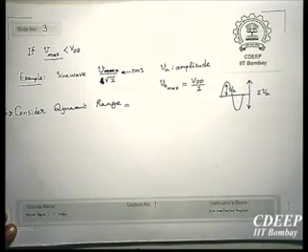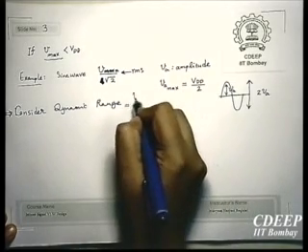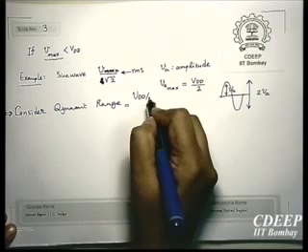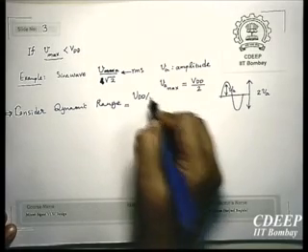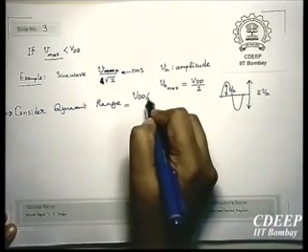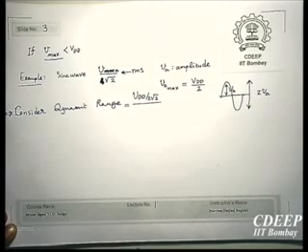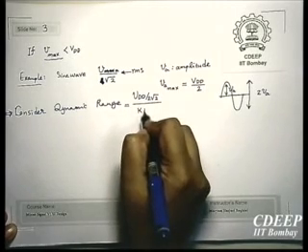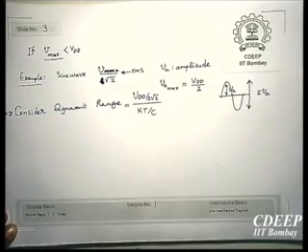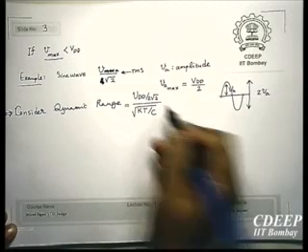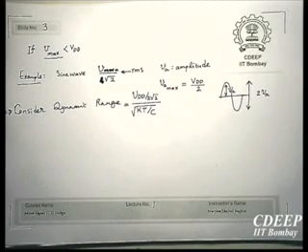In the case of a simple RC circuit with a sine wave at the input, it is VDD by 2 square root 2 divided by the RMS value of noise, square root of KT by C. It is the ratio of maximum RMS value to minimum RMS value.